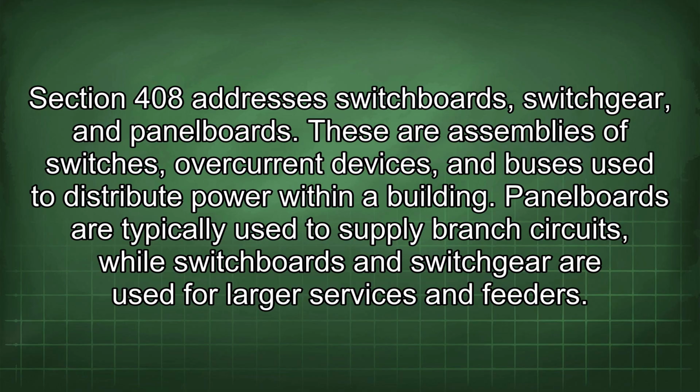Section 408 addresses switchboards, switchgear, and panelboards. These are assemblies of switches, overcurrent devices, and buses used to distribute power within a building. Panelboards are typically used to supply branch circuits, while switchboards and switchgear are used for larger services and feeders.